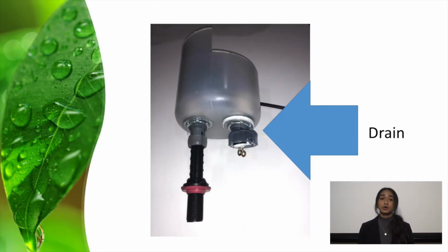Note that the gray water receiving tank must have a drain hole so that when there is not a gray water supply after flushing, the small tank will be emptied to let the fresh water flow in. The drain hole has some specific requirements, as the following. It cannot be too big, to ensure that the water does not drain too quickly from the gray water receiving tank during flushing as long as the gray water is available. It also cannot be too small, because that will create a long delay in filling the tank when the gray water is unavailable.